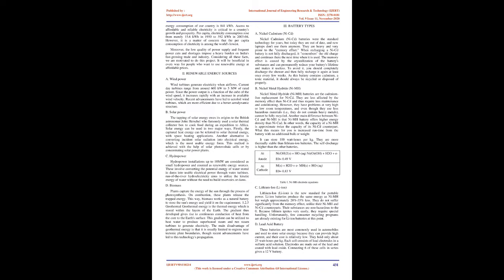This problem gets avoided in the incremental conductance method as the algorithm takes two samples of voltage and current to figure MPPT. However, despite higher efficiency, the algorithm's complexity is very high compared to the previous one, and hence the cost of implementation increases. So we have to mitigate with a trade-off between complexity and efficiency. It has been observed that the efficiency of the system also depends upon the converter. Typically it is maximum for a buck topology, then for buck-boost topology, and minimum for a boost topology. It is straightforward to implement and has high efficiency both under stationary and time-varying atmospheric conditions.